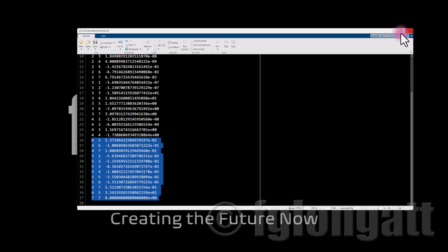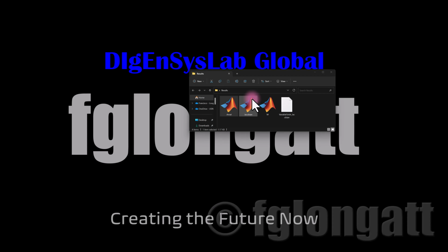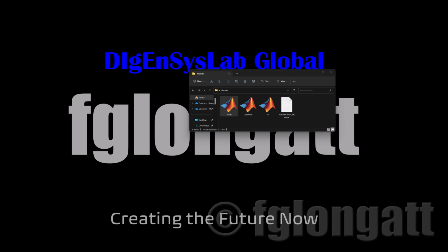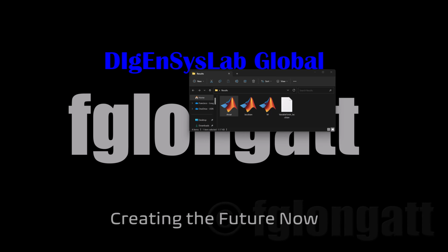So right now I show you that yes, you can export the system matrix, but the matrix that you can get directly from the modal analysis is the state matrix. I am sorry to tell you, but the matrix B, C, and D, they are not available, at least to the current version of the DIgSILENT PowerFactory. They are not available for the users, okay? And this is related with the way that PowerFactory is calculating the linearized model, okay?